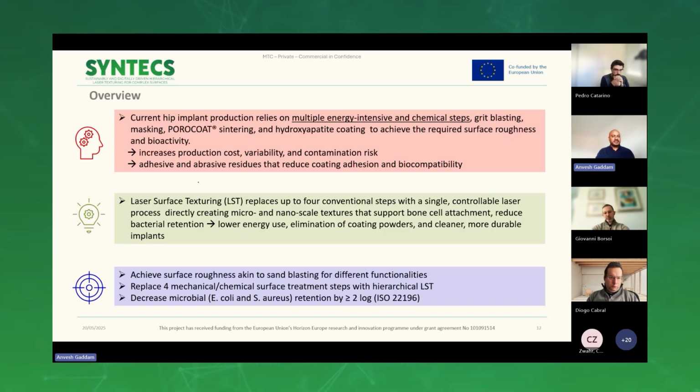Because of these multiple steps, the production cost is increased, and due to the powder coating and other non-deterministic steps like grit blasting, the variability is higher, and there is also contamination risk with the grit blasting as well. Accordingly, the adhesive and abrasive residue deposited on the coat will impact the biocompatibility. And in the SYNTECS project, laser surface texturing is intended to replace all these conventional steps with a single